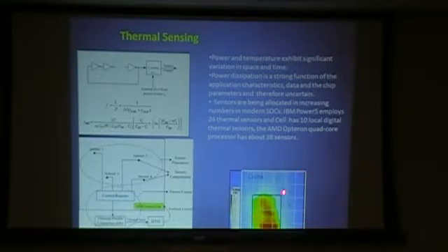Well, I have some sensors present on chip, and these sensors provide online data pertaining to the temperature at each of these points. And from that, I'd like to estimate the entire thermal profile of the chip. That's called the thermal profile estimation problem.